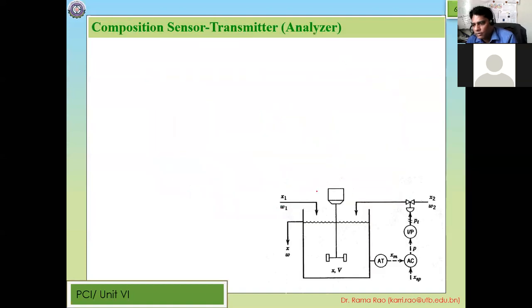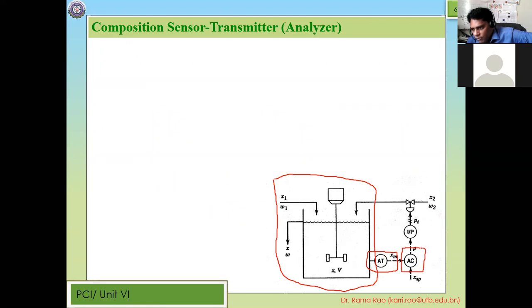So now what we have done is we just drew a block diagram only for this process. Now we need to derive for each component. That means we have a sensor, we have a controller. So we should have one block diagram for the controller, one block diagram for the sensor, and one block diagram for the final control element.